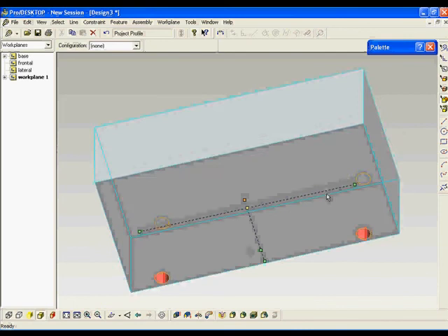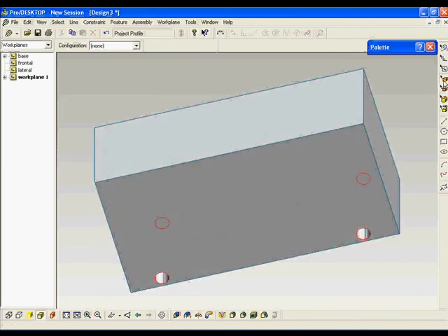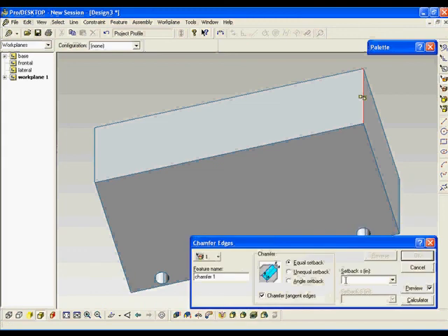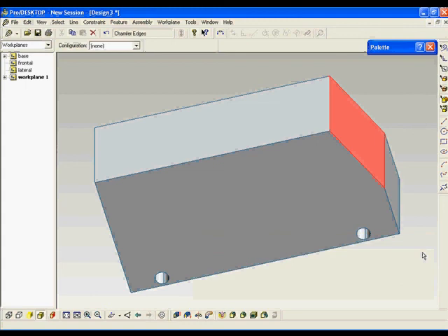The next step would be to go in and select one of the edges so we can create the windshield for the van body. And how we're going to create that is using the chamfer command, and we're going to set up two lines, one in the X direction of 30 inches, another one in the Y direction 40 inches, and we're going to cut between those two lines at an angle. This becomes the starting of your windshield for the front of your van body.